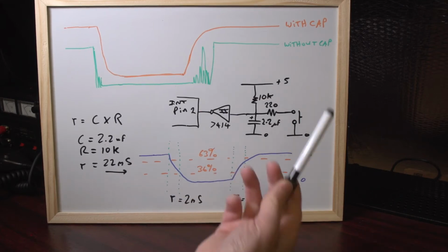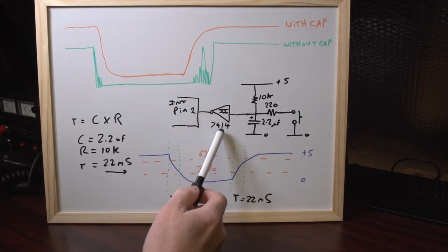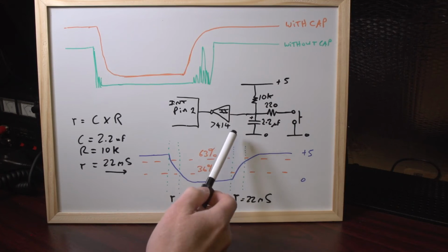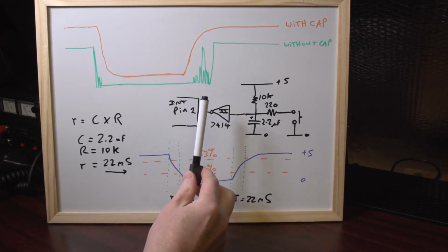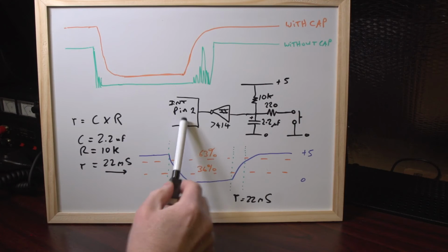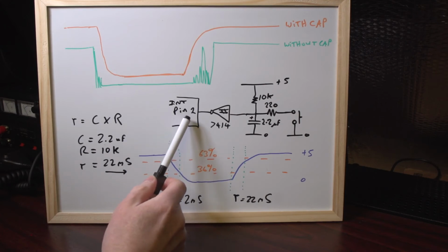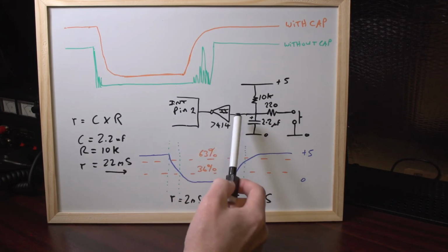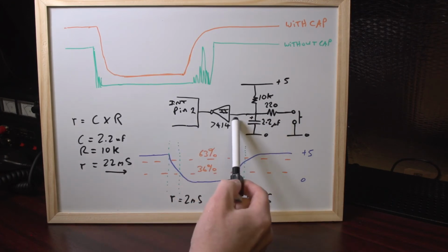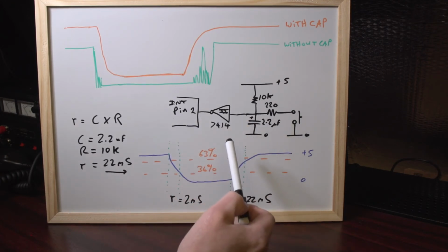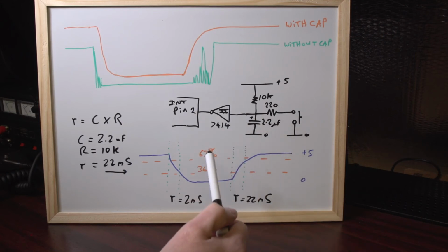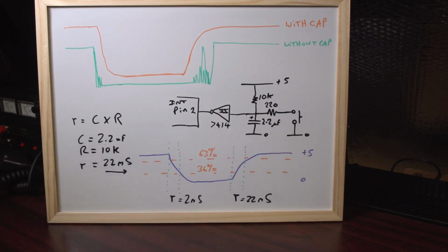But anyway, the solution is to use the 7414 for two reasons. First, the very fast rise time, like I've just been talking about, for the interrupt to actually work, because of the peculiarity of the chip. And second, it removes any input noise there could be by using a Schmitt trigger with different high and low detection voltages. Right, that is the hardware solution. So let's go and look at that in practice on the protoboard.